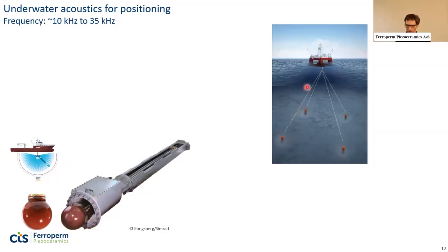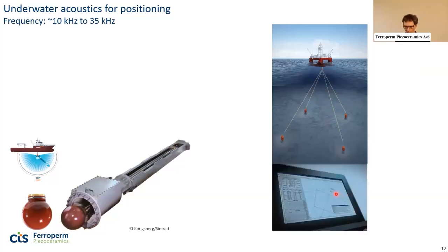Another case of application is for an oil rig like this, where you may need a very high precision. So here you have 4 transponders, and you can actually get the distance and the bearing relative to all 4 transponders at once, and you'll get some kind of screen view like this, where you can see the direction and the distance to all the transponders that are within range.